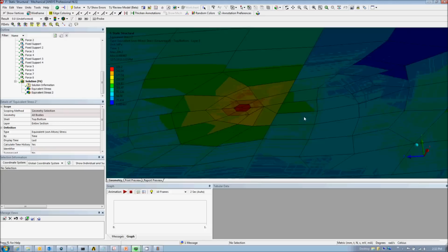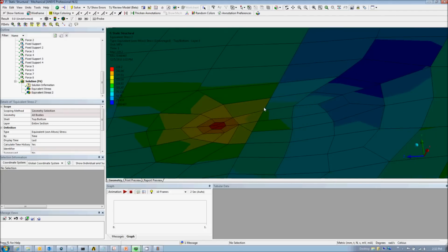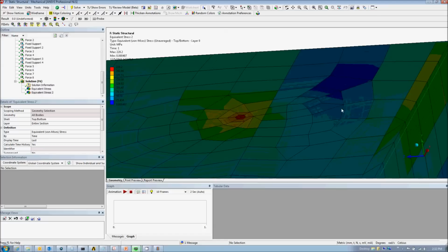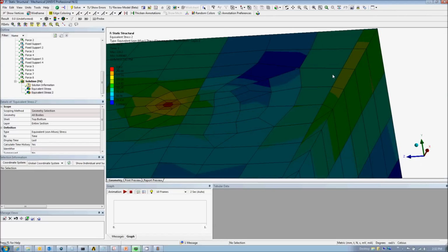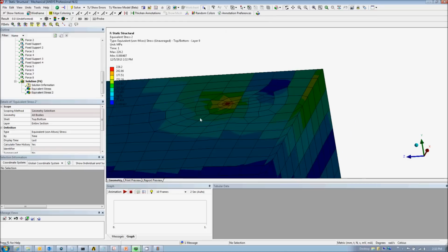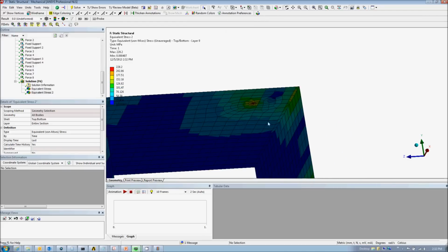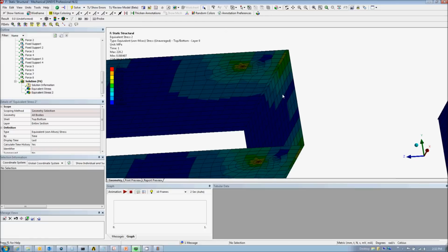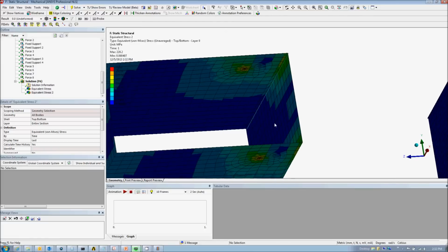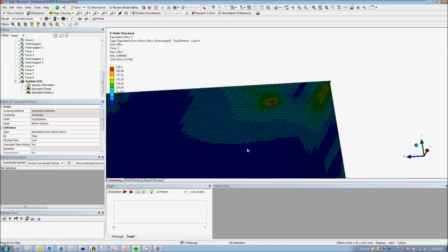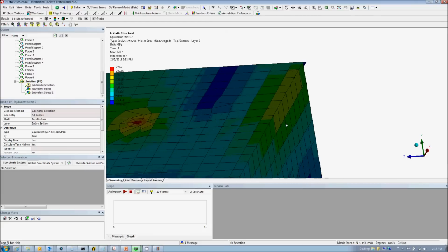We can also take a look at unaveraged stress results. What we might be looking for here are areas where the color bands skip several bands in between. There's not a continuous transition between adjacent bands on the legend. Like most other results interpretation, this is quite subjective, but one practice to use would be to keep the default 9 color bands and look at the stress values from 0 to your critical area of interest.